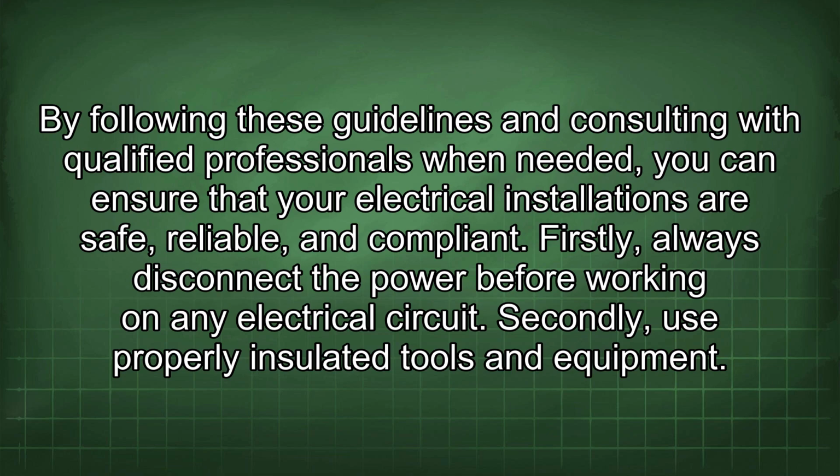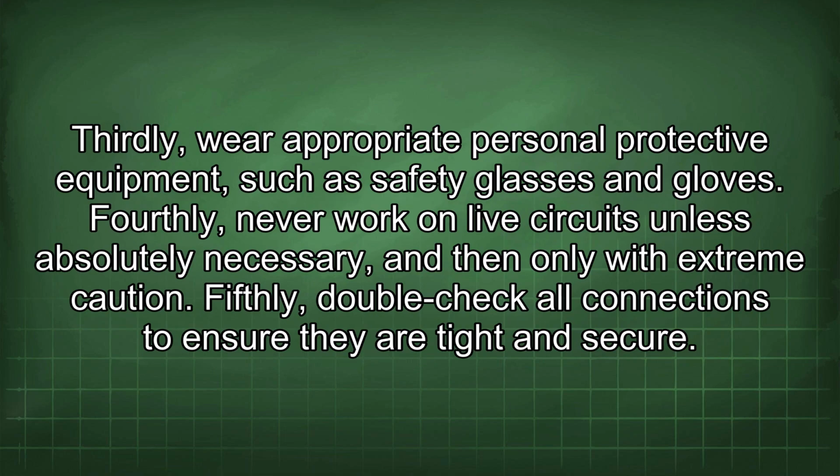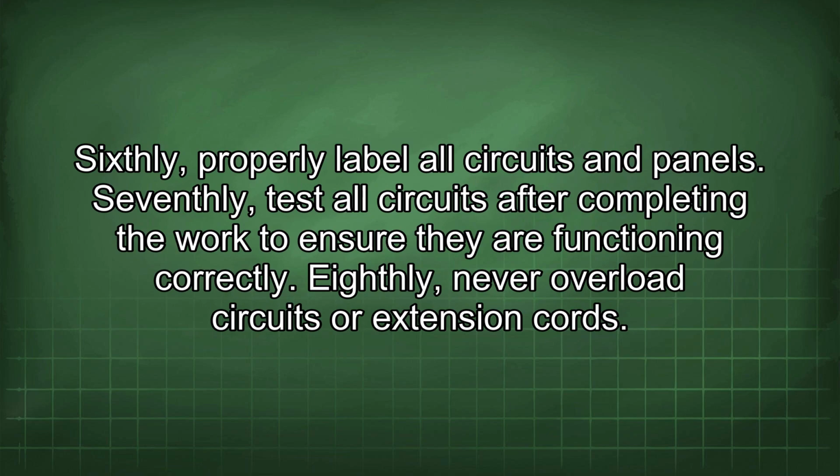Firstly, always disconnect the power before working on any electrical circuit. Secondly, use properly insulated tools and equipment. Thirdly, wear appropriate personal protective equipment, such as safety glasses and gloves. Fourthly, never work on live circuits unless absolutely necessary, and then only with extreme caution. Fifthly, double-check all connections to ensure they are tight and secure. Sixthly, properly label all circuits and panels.